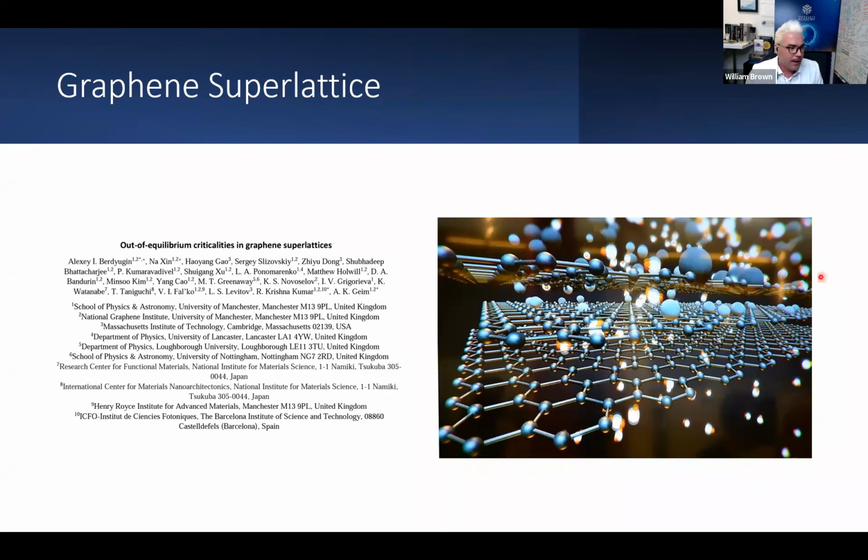Now, graphene has become a focus of materials scientists' research as it has remarkable structural and electronic properties. For example, it can carry huge current densities, about 10 to the 8 amps per square centimeter, roughly 2 orders of magnitude greater than copper. And even though it occurs in these single planar honeycomb configurations or sheets, it's remarkably strong. If rolled into a carbon nanotube, it's stronger than steel.